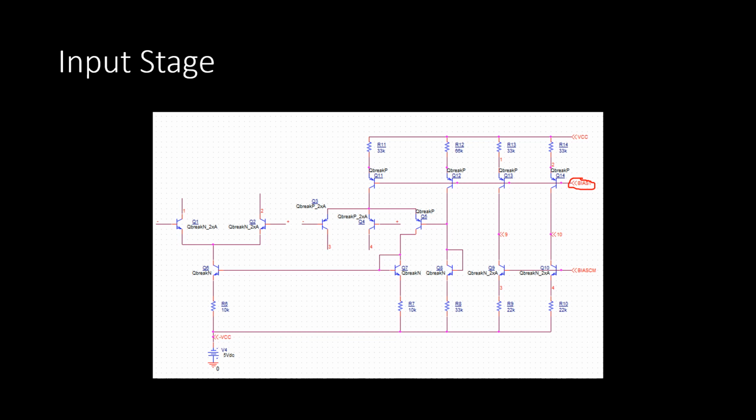This is used to apply a 6 microamp bias at nodes 1 and 2, which biases the differential amplifier at the inverting and non-inverting inputs, at least the NPN side of the inverting and non-inverting inputs. These inputs are also coupled to two PNP transistors, which are biased at bias points 3 and 4.